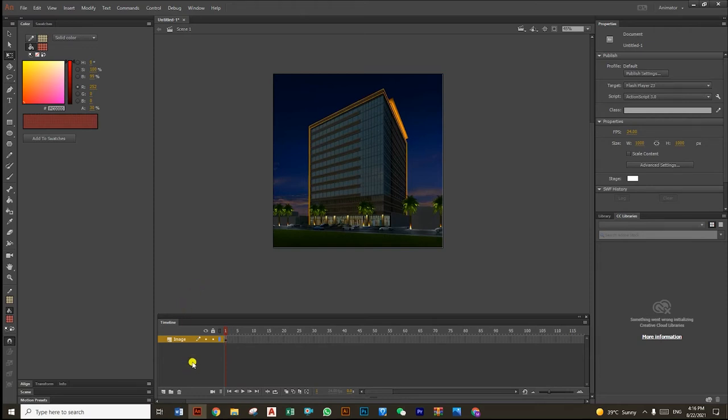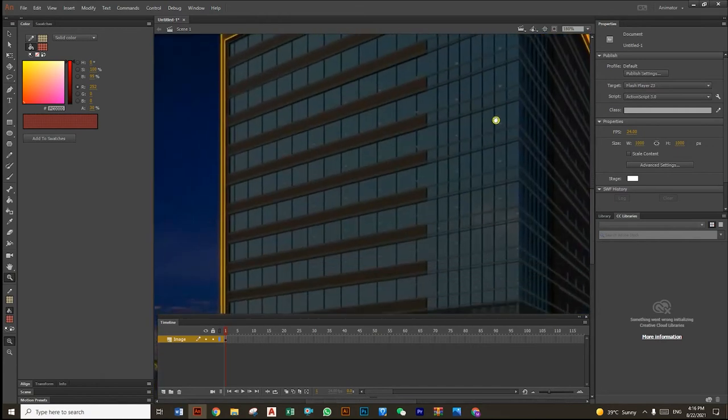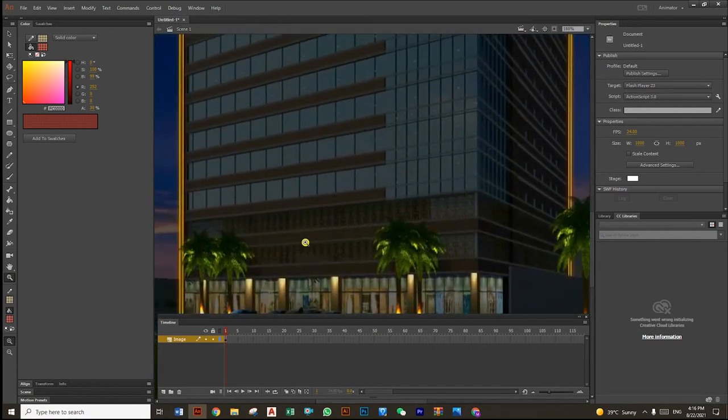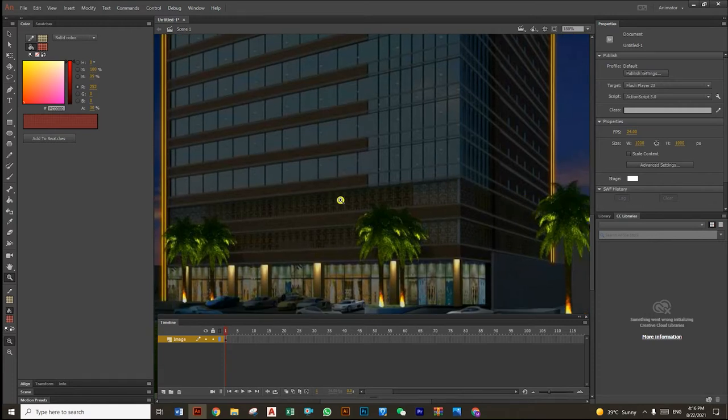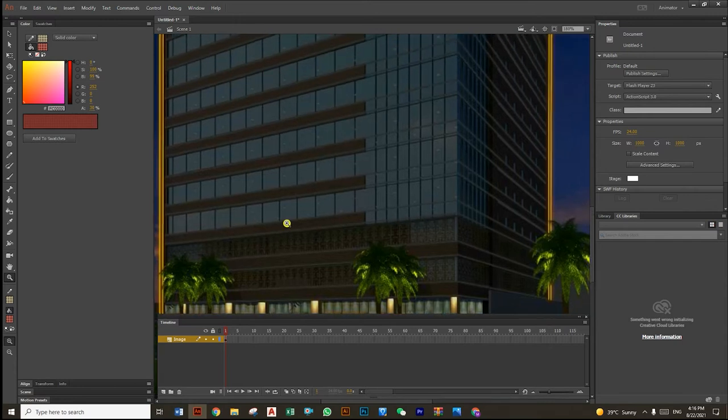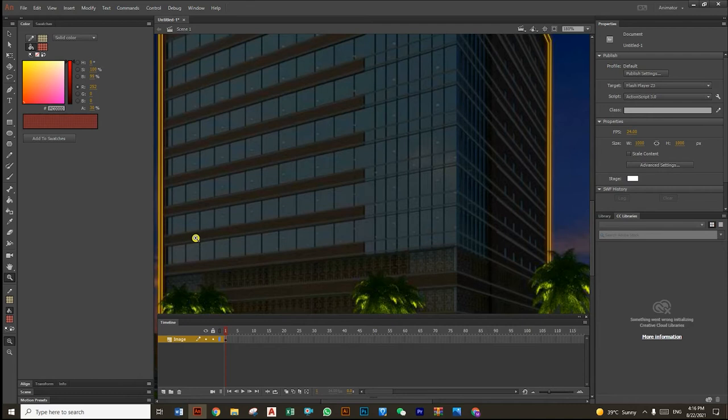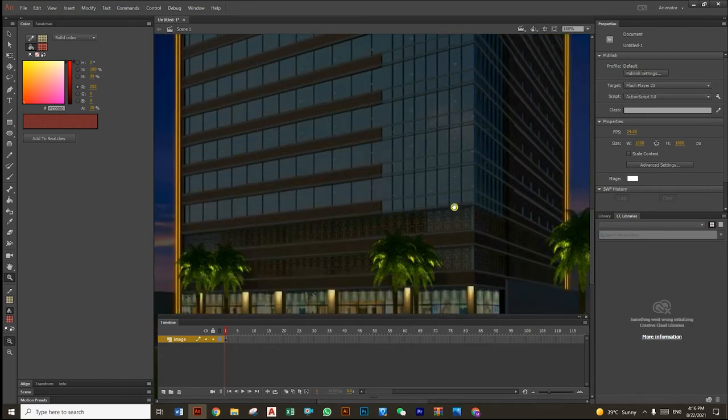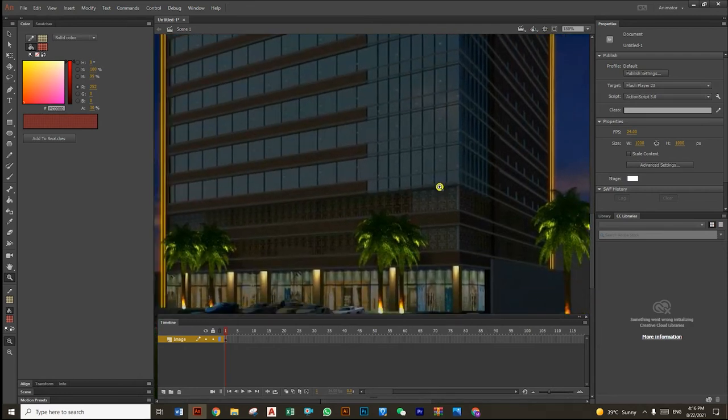Now what we need to do is understand where we want the light. So when thinking of two lines of this, you can see there is a horizontal line, an aluminum profile is there. So we'll use our LEDs in those profiles. We need to show the client that we are going to show RGB lights in this profile. So for that, what we need to do is create the lines. So for that, now we'll take another new layer.